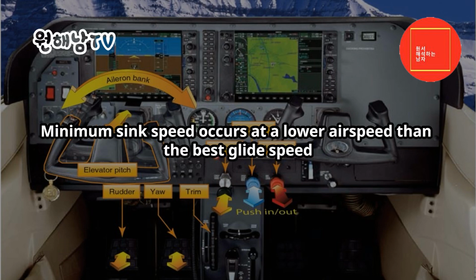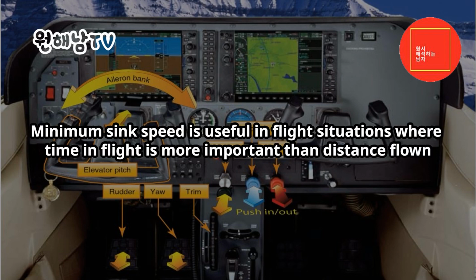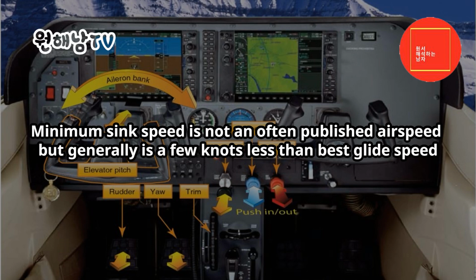It results in the airplane losing altitude at the lowest rate. Minimum sink speed occurs at a lower airspeed than the best glide speed. Flight at the minimum sink airspeed results in less distance traveled. Minimum sink speed is useful in flight situations where time in flight is more important than distance flown. An example is ditching an airplane at sea. Minimum sink speed is not an often published airspeed, but generally is a few knots less than best glide speed.